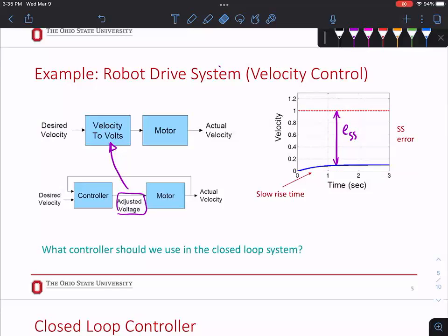steady state error. This is really important because designing a PID with all 3 terms is expensive, because you have to tune all 3 of them. It takes more time and it impacts the components of your system. Literally, you have to buy a more expensive motor to be able to run the system based on your controller, right? So you have to pick the exact one that fixes the problem for you. So one is that we know you have to get rid of the error.